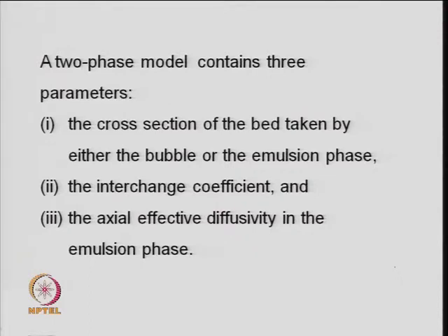So, if I talk only about a two phase model, in the two phase model we just consider the cross section of the bed which is taken either by the bubble or by the emulsion. So, what fraction has been taken by the emulsion phase and what fraction of the bed has been taken by the bubble, because we are not considering any other phase, right. So, this is one parameter, the fraction of the bubbles in each phase.